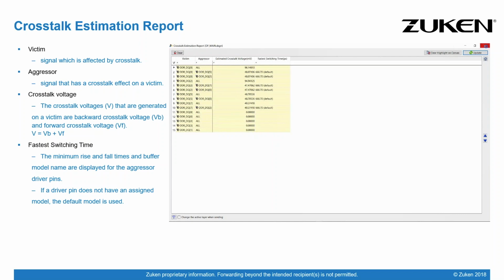This is not just trace-to-trace crosstalk, which happens when you have two traces very close together. This is crosstalk because you have many signal vias sharing one common ground via. So why is crosstalk so important in DDR5 designing? Technically, traces that are routed in parallel will form a coupling capacitance and coupling inductance, and both of these depend on the distance of the traces and the dielectric environment, and the length over which the traces are routed. The closer together the traces are, and the longer they run in parallel, the more coupling. The amplitude of the crosstalk depends on the rise and fall time of the aggressor signals, which means the same PCB layout might perform better or worse sometimes.